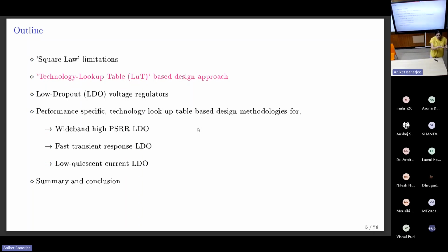So I started with square law and look at the simulation result. Oh my God, there's a mismatch. The next step I do is, okay, maybe let me see what, if not square law, there is some model that's fitting. Then I realized, oh my God, that's even not working because it will be a function. They keep changing. If you change VOV, W, what all do I do? It's not going to fit. So what's the other thing that I can do?